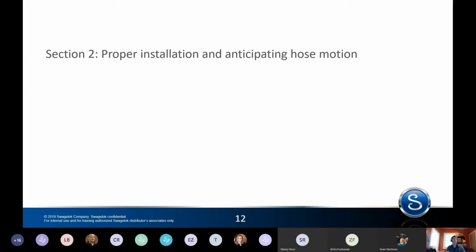Yeah, in general, the most common temperature we see is about 60 degrees Celsius, which I believe is about 130 degrees Fahrenheit, maybe 140, is safe to touch. So if you have a steam, which many times, all the time, steam is above that temperature, and a lot of media is above that temperature, we recommend to have insulation on the outside of a hose.